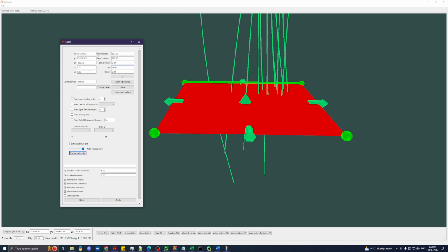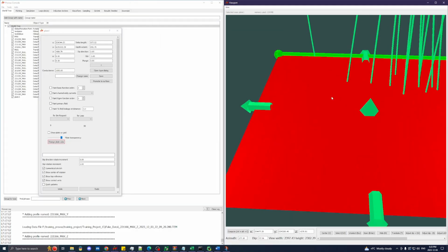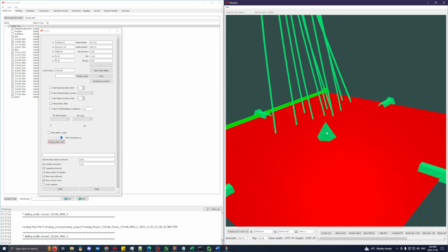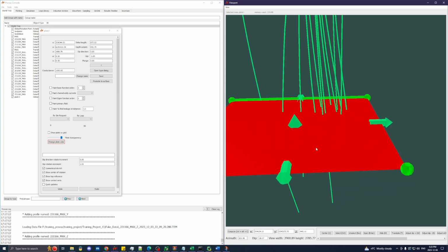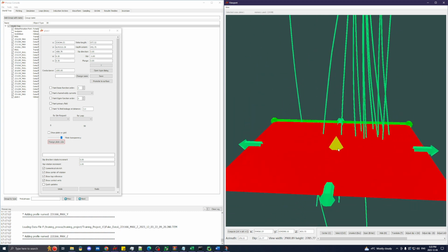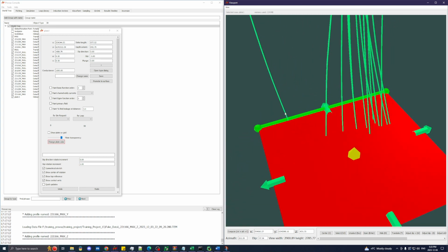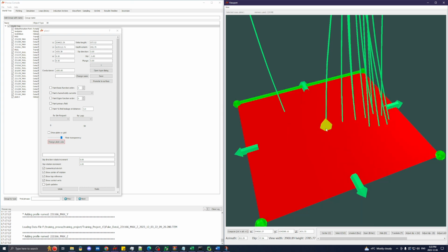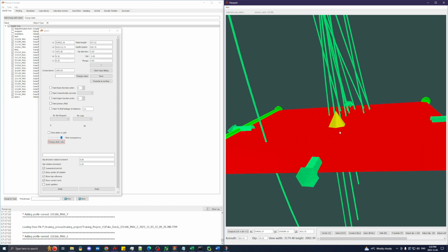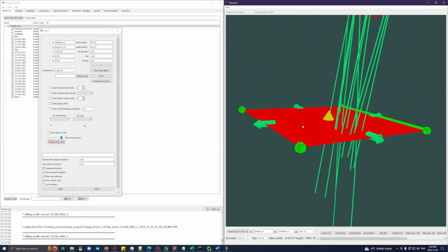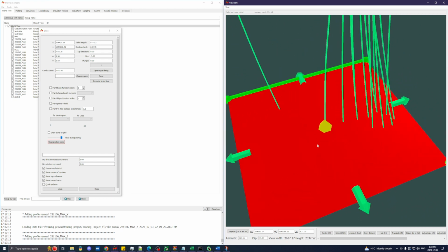So I've talked about most of these, but what about the U and the V? You'll notice our plate here has this pyramid in the center, and this is the center of rotation for the plate. Why this might be useful is, if you highlight this pyramid by control left click, and hold Z and left click this center of rotation, you're able to move it such that I've now put the center of rotation in the hole. And I'll show you why that's useful in a second.